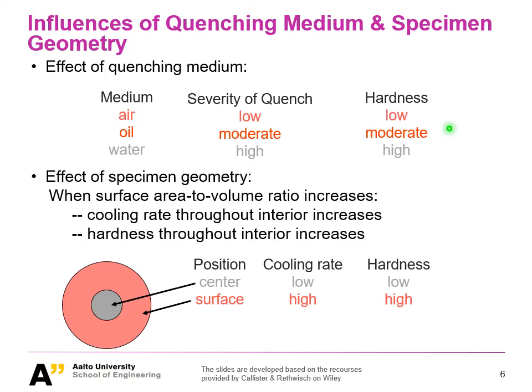But think about it, if you have a massive product, it is large, and especially the thickness is high. That will mean the cooling rate will not be uniform. The center will definitely have a lower cooling rate than the surface, right? I mean, you don't have the knowledge about heat transfer yet, most likely, but I think from daily practice, you would be able to sense it, right?